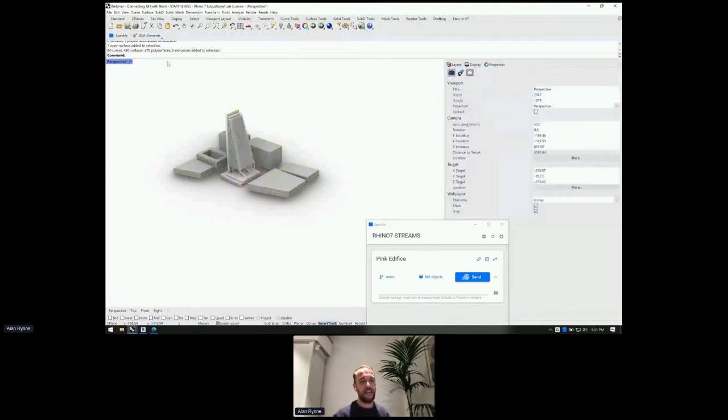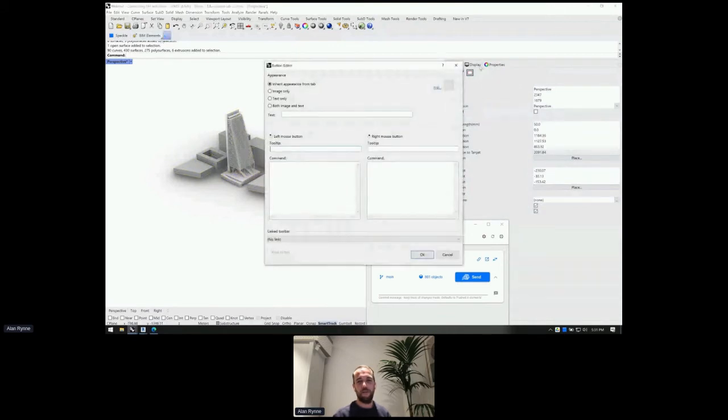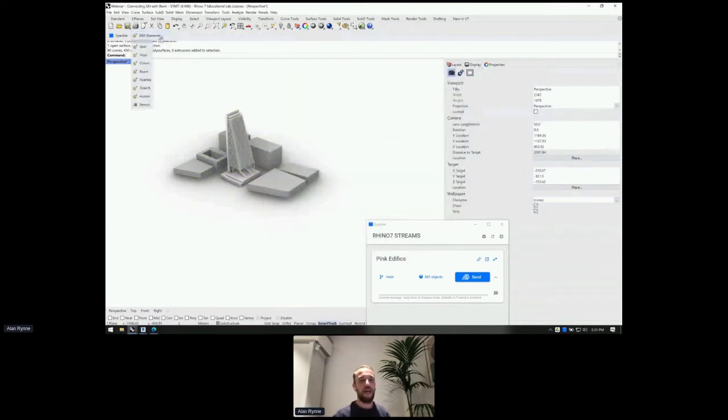So let's give a go at this. Oh, sorry, I hit the wrong place. And say, okay, I want all of this model to be automatic. So I want Speckle to decide what type of geometry this represents in Revit. If it's a flat geometry, horizontal, it's going to assume it's a floor. If it's a vertical flat, it's going to assume it's a wall. Very common sense things. If you send a line, it will assume it's a beam or a column, depending on its orientation.